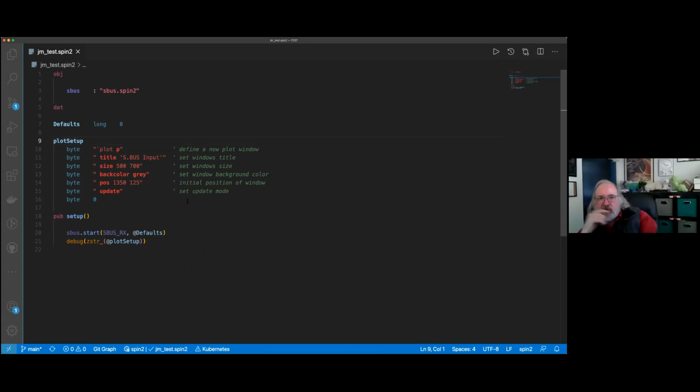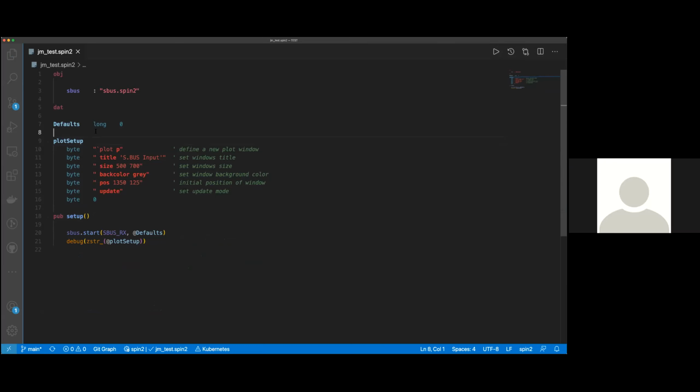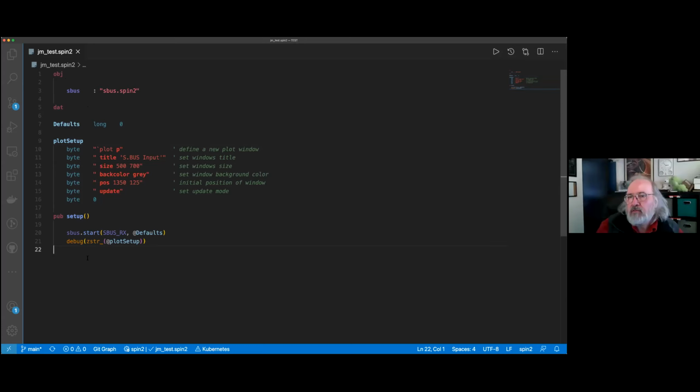Yes, so you'd have to have a format from memory to memory to format the numbers. But we have string formatting routines that we could probably use. Correct. Generate a string on the fly and send it out. Yeah, just write to an output pointer or memory pointer instead of the debug port.